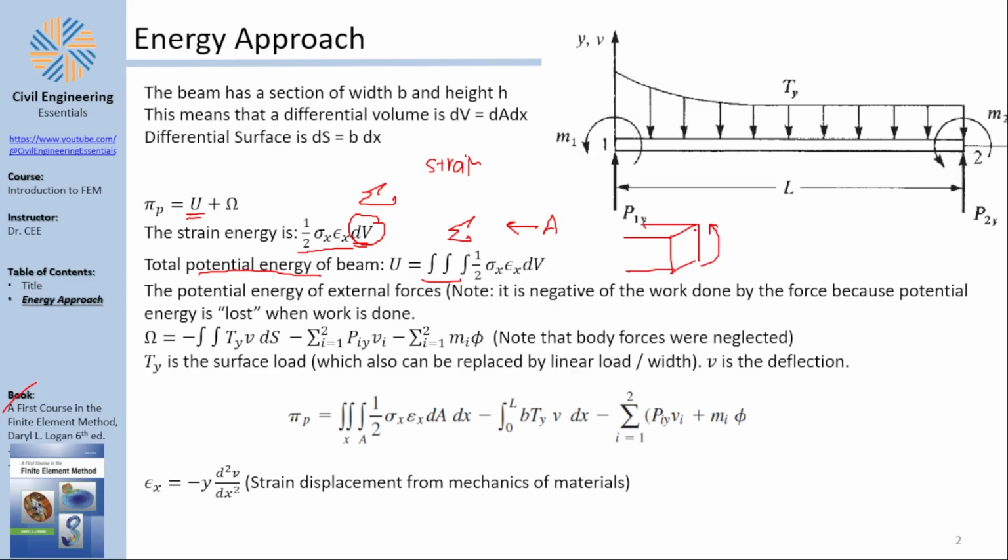And the bending moment causes compression on some sides and tensile stresses on some sides. Like it would cause some compression stresses on one side and tensile stresses on the other side, meaning that the stress is a variable along the area even, and the strain is a variable along the area. And for a case of uniaxial bending, the stress and strain would be constant for the width. But in a case of biaxial bending, you would have a variability of the stress and the strain on every point. Like if you go in the length, there is a change in sigma and epsilon because moment changes.